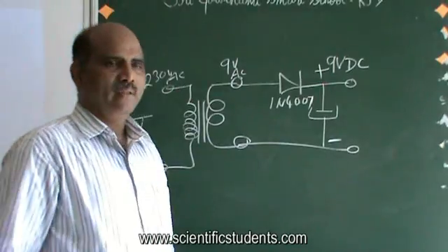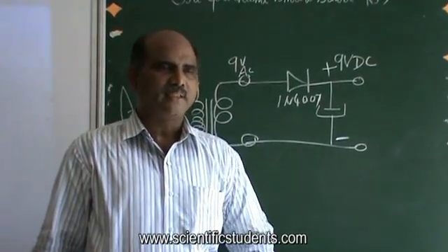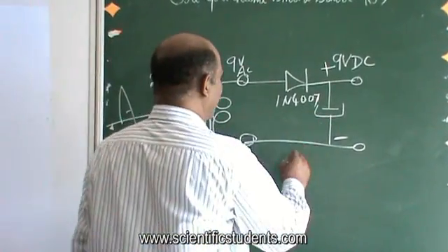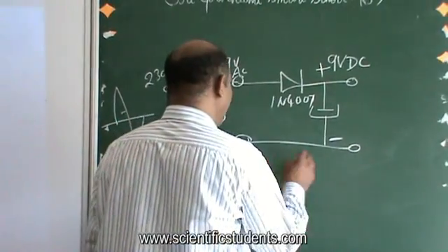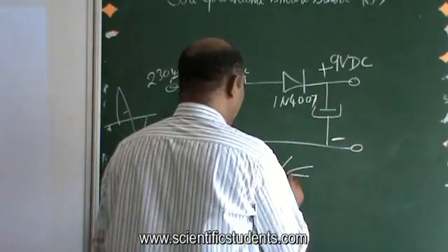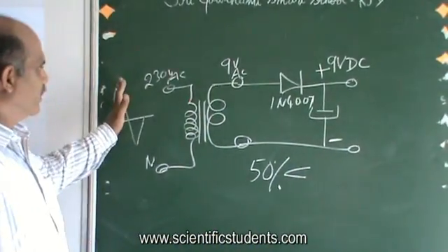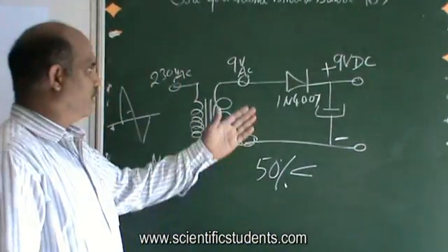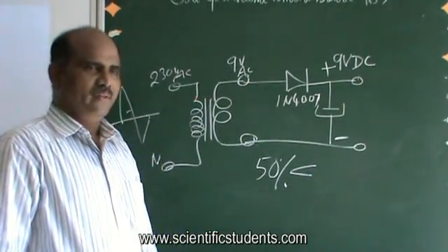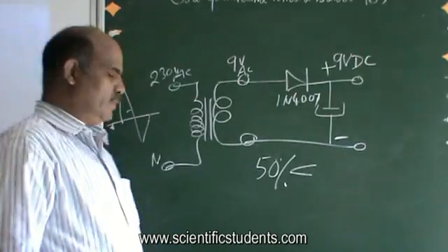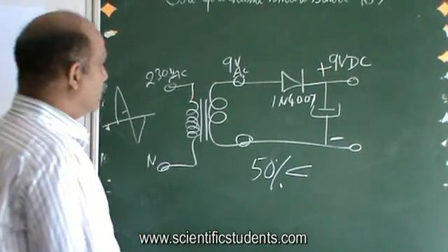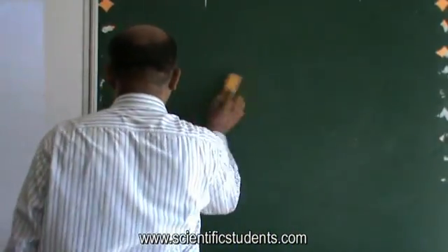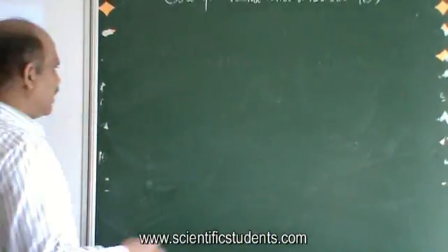But still, as a half-wave rectifier, it is not that pure, because efficiency is less than 50%. That means if you are using 100 watts here, you will be getting only 48 to 50 watts, because of single wave, half-wave rectification. Okay? So, what is the best alternative? But for simple, it is very simple, no? For which we have a little modification.